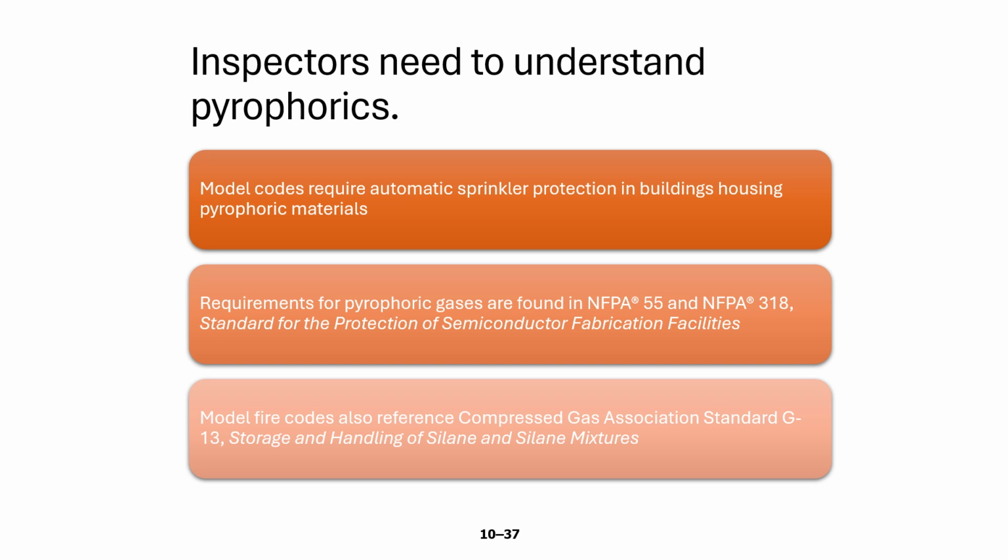In the case of alkali metals such as NaK, which is sodium potassium, or pyrophoric radioactive isotopes, the application of water can grow and spread the fire. So this is where we start looking at different types of special agents to control and hopefully extinguish fires involving pyrophoric materials.